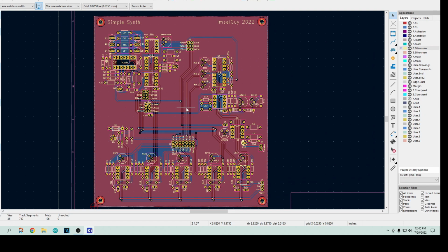My impressions of KiCAD: it's quite capable. It'll do what you need it to do. I have 2 main gripes. The first is you have to use 2 hands at all times in order to lay things out. You have to have one hand on the mouse, and one hand on the keyboard, hitting rotate, move, things like that. When I was laying out in Eagle, it was very rare that I needed to use my second hand. I could do almost everything from the mouse.